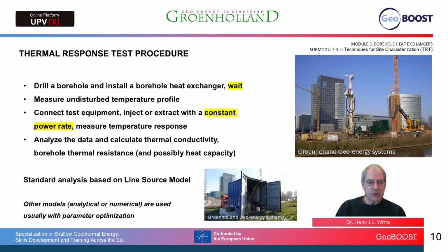Then you go back to site, you measure the undisturbed temperature profile, either with the test machine itself or with a temperature probe that you can lower down the heat exchanger, and you connect the test equipment and you start injecting or extracting heat with a constant power rate. This is very important in the standard test protocol, that you have a constant power rate. And you measure the temperature response of the fluid circulating in the borehole.